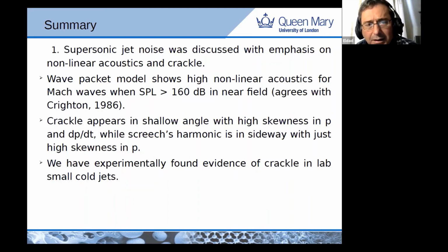It's really highly non-linear, but the other thing that we found is that the crackle can appear even from a non-random source. The sound can look like crackle. The difference between crackle and screech, that we found experimentally, is that in crackle we have high skewness both in P, in the pressure, and in the dP/dt, while screech has just high skewness in the pressure, not in the time derivative. And we found experimental evidence of crackle in a lab small cold jet.